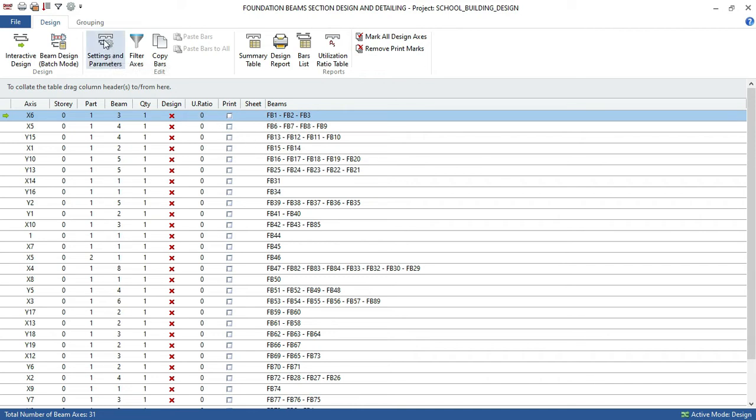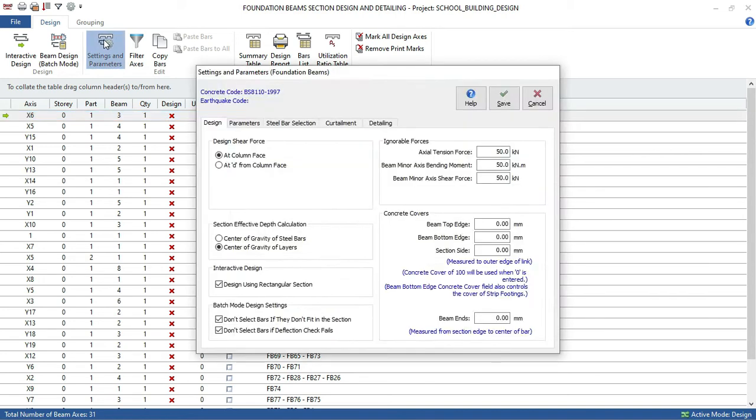So right now you have to go to this place, click first on this place. Now listen here very attentively. If you don't do these settings here, there is no way your beam will design. If you don't put these cover values, it will not design. And you put your cover values in this sequence. You put for the edge the 35, and then you put here 50, and then here 35. If you don't put these values this way for your cover, this beam will not design.